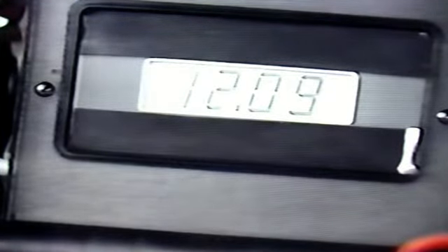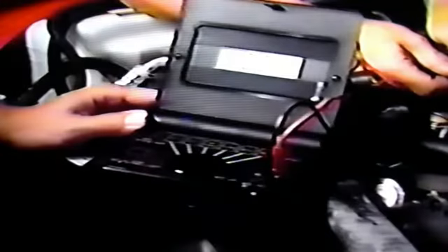And again, there's a choice of under or over 10 volts to determine the next procedure. We find that the next step is to check mixture control solenoid resistance at the carburetor. To accomplish this, we first disconnect the mixture control solenoid from the carburetor. Then, switch the meter from volt readings to ohm readings and check the solenoid resistance. The meter shows an MC solenoid resistance of 23.4 ohms.